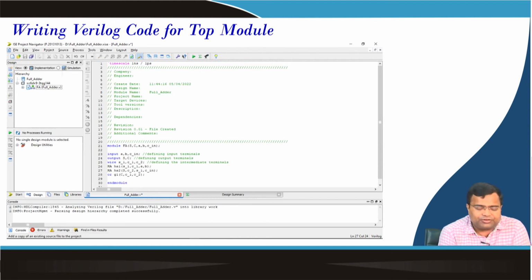Next, now you fill up with your Verilog code. That means if you want to write a full adder, first you can see the sum block. If it is not clearly visible, I am writing here module, then it is the name as the full adder. So, here the module name is again different, because we have the full adder.v file, but it is better to maintain the same name rather than naming another name.